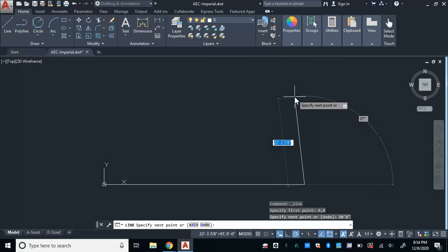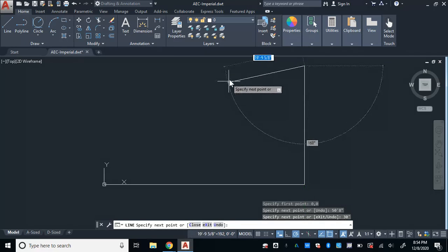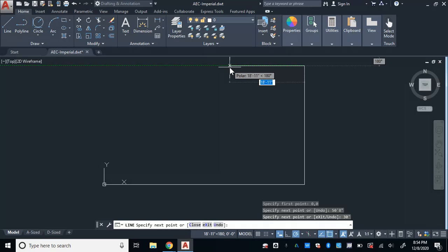Also notice I'm not putting the fillet in, that rounded curve. It says in the book here the radius is 10 feet. I'm going to add that curve with the fillet command after I'm done drawing the outside perimeter of my house walls. It's easier to do it that way. It goes up 30 feet and then it cuts to the left 20 foot 8 inches.